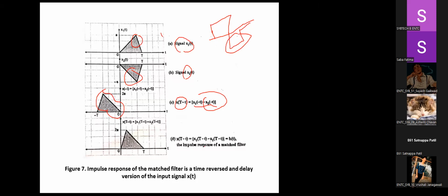Then this entire information, again I'm going to reverse it. You can express it either in this particular form. Here you are taking minus t, right? Here again minus t. So when we shift it, that is e raised to minus j 2 pi fT, when we shift it, we get a positive impulse.